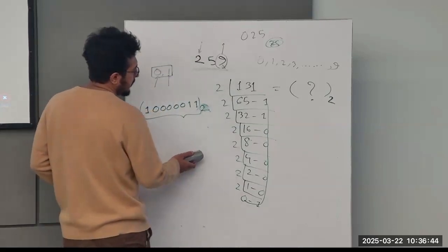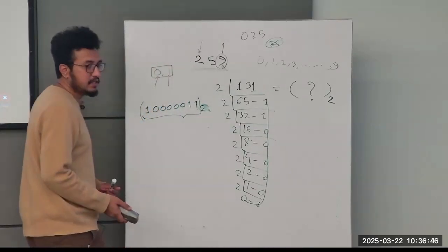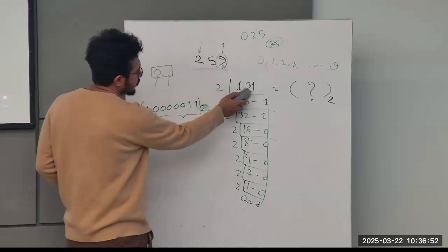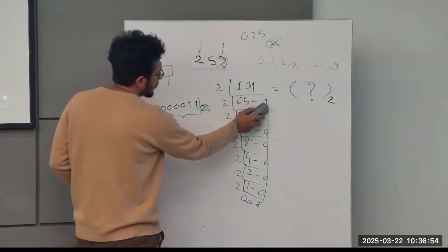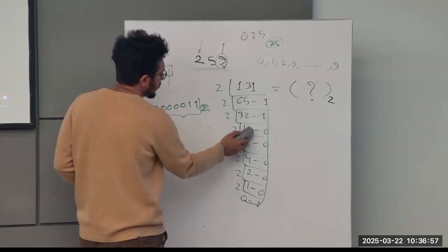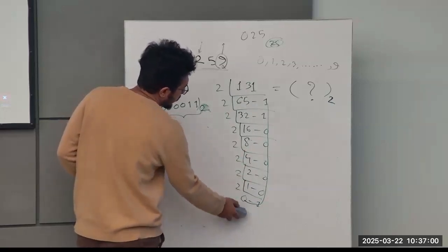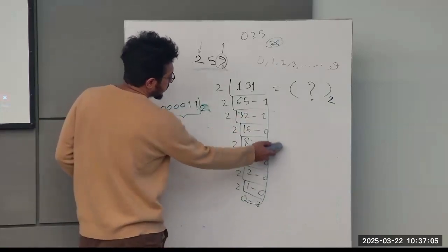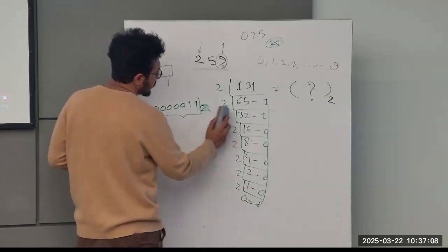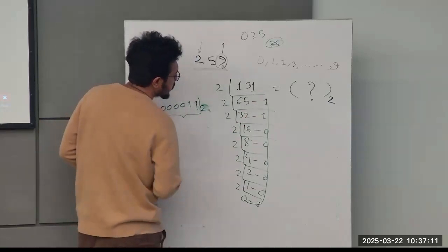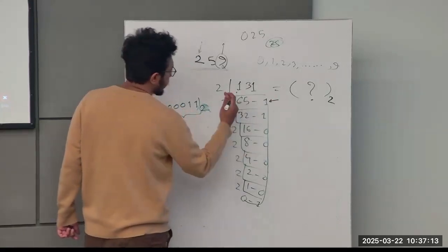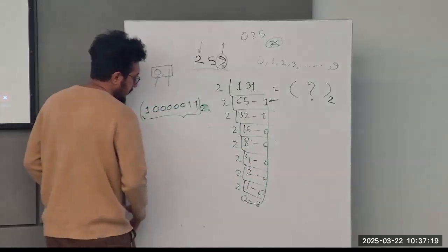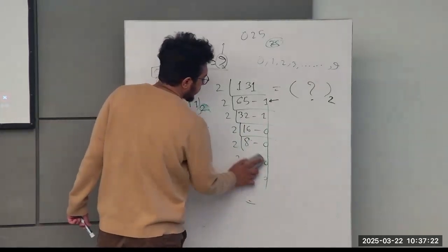So if I now give you any decimal number, you can easily convert it to a binary number, right? That is really easy. Just divide by 2 and note the division result and the remainder. Put it this way, and when you get 0, 1, you already know that it's done. Then just read in this direction, from right to left. This is your least significant digit, the rightmost digit, and this is the leftmost digit. This way you can convert any decimal number into binary digits.